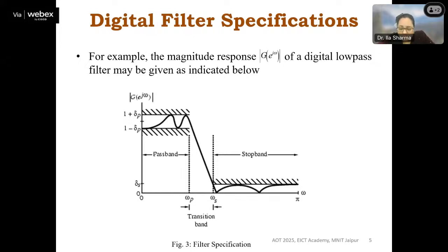So this is how we create objective functions that involve all these operations in the passband and in the stop band, and then we formulate this objective function or cost function according to our need. After that, any optimization technique, whether PSO or ABC, can be employed to achieve the minimum or maximum value according to our cost function.